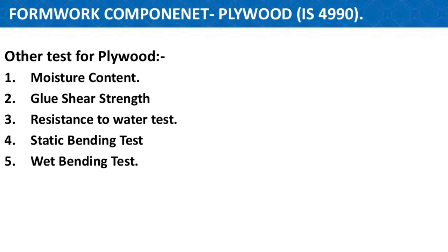These are also required because plywood is pasted with glue. So you need to know that during concreting, placement or handling, this glue should not be removed. So glue shear strength is important, and so is the resistance to water test, because whenever you are working outside there is water, so you also need to find out the resistance. These are the tests you need to carry out for plywood.